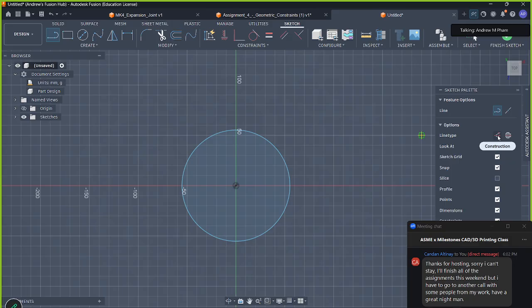It allows us to build some kind of foundation in our sketch. But when we go to manipulate it into something like an extrusion, Fusion will ignore these geometries, and it'll allow us to have more full closed bodies instead.